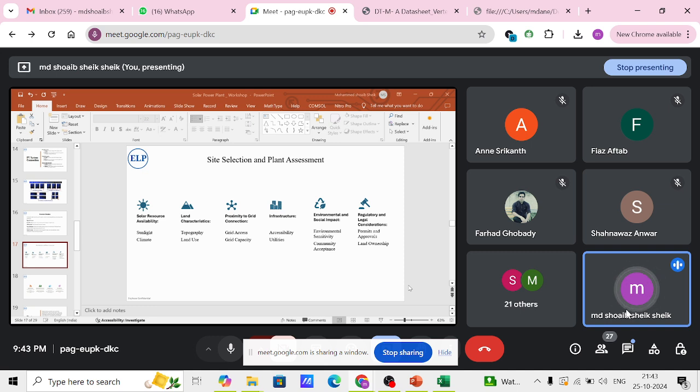First, we need to check what the sunlight is throughout the year, whether we have good sunlight at their location, or whether it is completely rainy season for 6 months in a year. If you have 6 months of rain, as in winter, and you are not getting sunlight, it is a failure project. You can directly inform them of that. So this is the scenario where you can generate electricity for only 6 months. After that, you will not be producing any amount of energy. But you have to understand the sunlight and the climate of that place. This is the first thing before going for any installation.